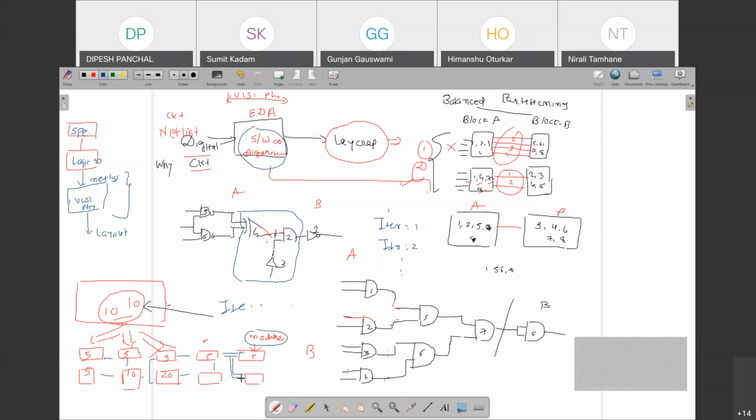Gate level netlist means all of this diagram. In the diagram we have this input, this connection; that is called the netlist. This is not the actual starting of the chapter; later on we have some terminology also. If I give you this circuit, write down the netlist manually. That is also possible, we'll see later on. So this netlist acts as the input to the partitioning, and as output of partitioning we get different sub modules as well as interconnection information.